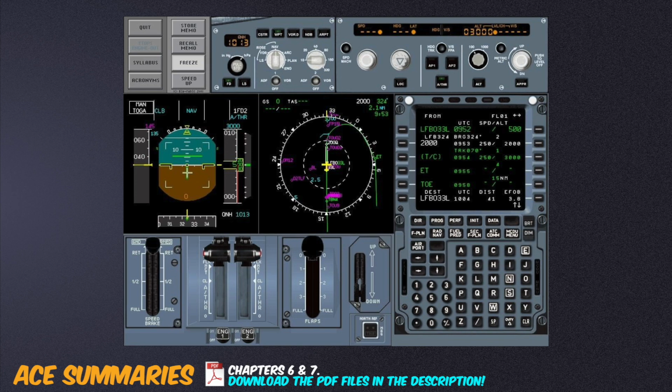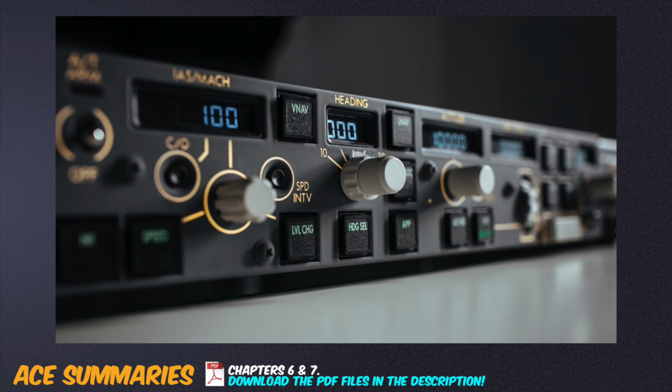LNAV and VNAV, which stand for lateral and vertical navigation respectively, are modes of the FMS, which can be selected as guidance in manual flying or can be selected to govern the autopilot and autothrottle systems. The flight management system contains company routes which may be amended by the flight crew. The autopilot stabilization capability is broken down into 3 control systems: pitch, roll, and yaw. The autopilot's maneuvering capabilities are classified according to the number of axes which it can control.